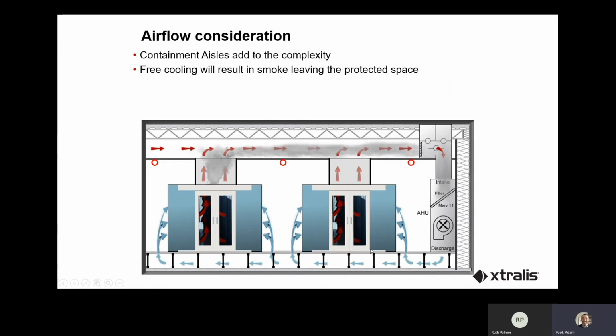But actually, to compound the problem yet further, if free cooling is deployed, where we're drawing air in from outside because it's more efficient to use colder external air than it is cooling the air inside the space, then any smoke is immediately going to be taken out of the facility and even more lost than if it was going through the air handling process. So this is critical from a design perspective when people are looking at air handling systems or fire detection within data centers: fully understanding what the airflow characteristics are, what's occurring with that airflow.